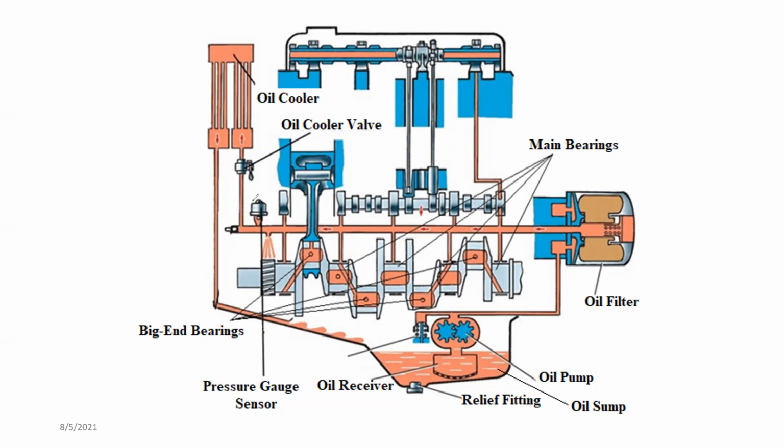In addition to that, you have an oil cooler here. As I told you earlier, in some cases oil coolers are used. In the oil cooler you have a valve here. This is not a valve used in all engines, only in some particular engines. This oil cooler valve is very much similar to the thermostat valve used in the engine cooling system.